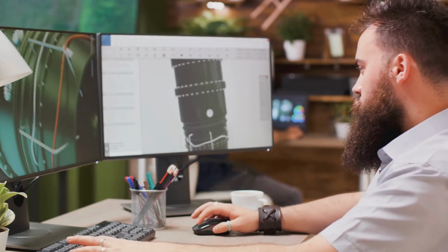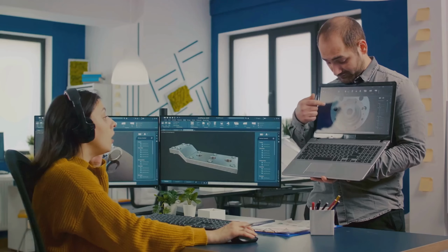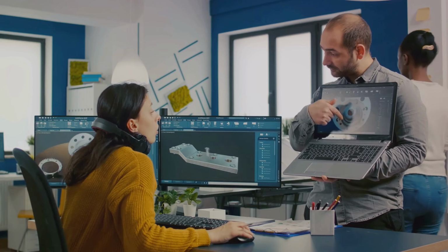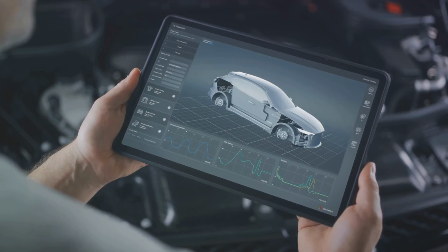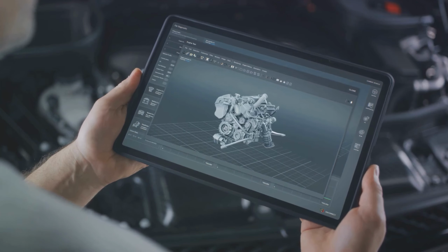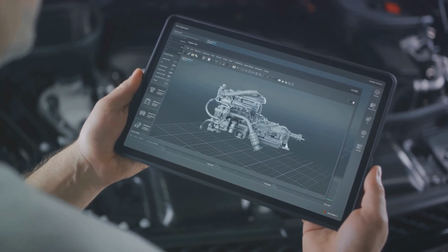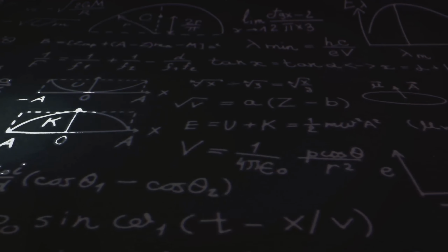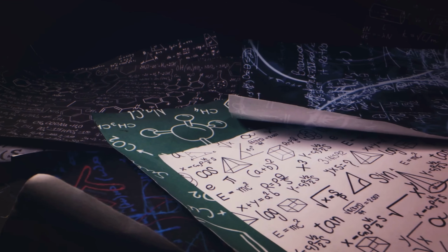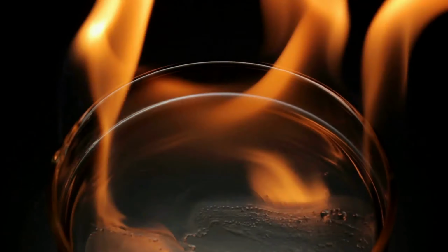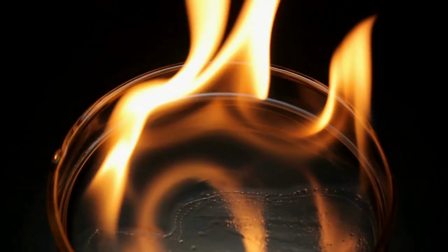It supports a range of combustion models such as premixed, non-premixed, and partially premixed combustion. Importantly, ANSYS Fluent can predict the formation and emission of pollutants like soot and NOx, which are critical for environmental and health considerations. Thus, ANSYS Fluent is a versatile tool for researchers and engineers working on combustion problems.